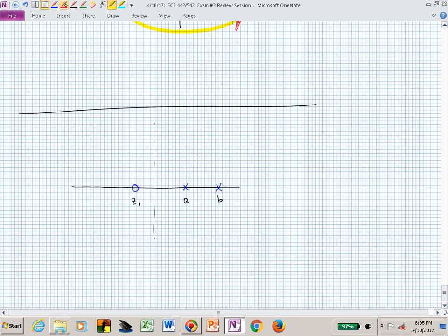And here's our classic, but now you should be good to go on this one. This is the special case, and I have a video and notes for this special case. This is 2 real poles to the right of 1 real zero. How do I find the breakaway? Very quickly. Geometric mean between the center, the Z1, and the 2 poles. So it'd be A minus Z1, that length, times B minus Z1, that length, square rooted. I now know my radius.